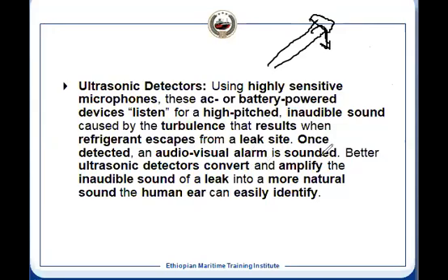So this is the way it is, and this can convert even into audio, visual, and alarm. It means it will give you an alarm, and also audio and visual. It will show on the display that there is a detection of a refrigerant leak, as well as give you audio so that you can hear a sound, like a beep. It means there is a leakage, and it is always converted into a natural sound which the human ear can easily identify, because we cannot identify all sounds. Those are the natural sounds which we can identify. So this is another way we can detect the gas.